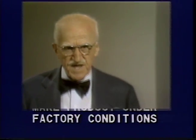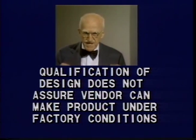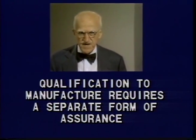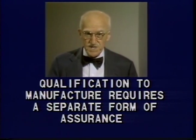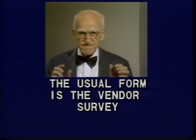Qualification testing of product design does not assure that the vendor is qualified to make the product to that design under factory conditions. Qualification to manufacture requires a separate form of quality assurance. The usual form is the vendor's survey, a visit to evaluate the vendor's capability for manufacture.